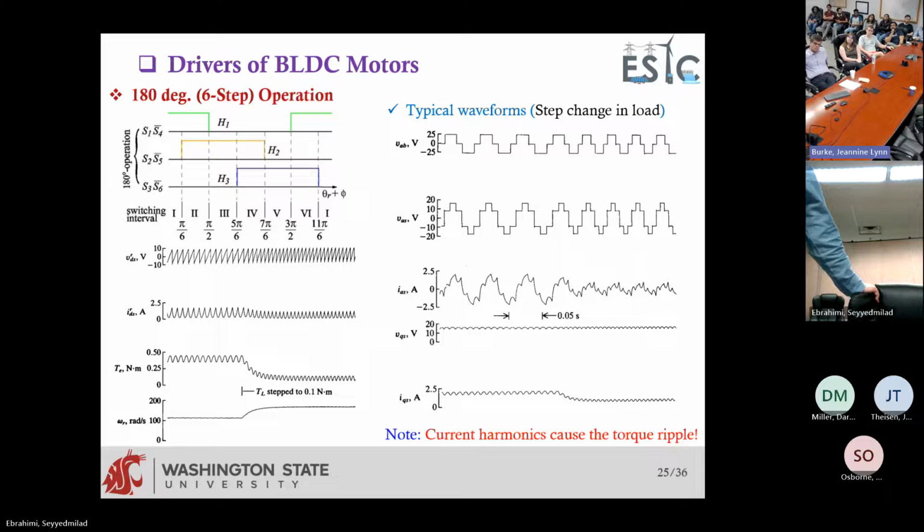These are not desirable because you want to operate with precise positioning control. So I want to, for example, rotate it smoothly, but it doesn't go like that. That's not what I'm looking for in position control, right? So I want to go as smoothly as possible, without much ripple. Otherwise, if the torque is high, it will jerk. Torque ripple also causes a speed ripple. The torque and speed are dependent; we look at those characteristics.